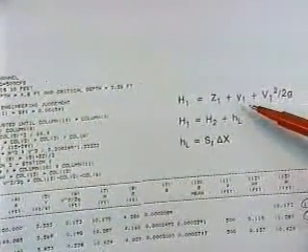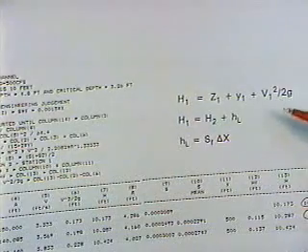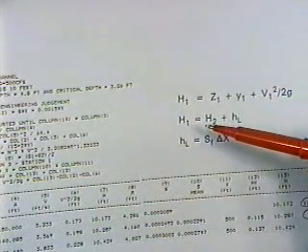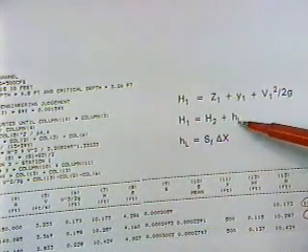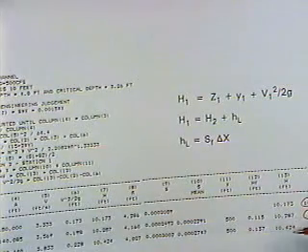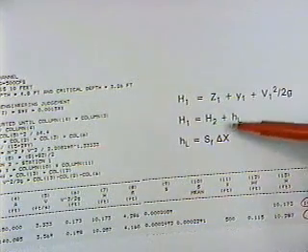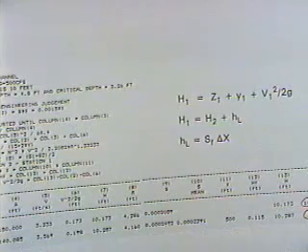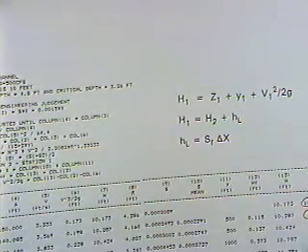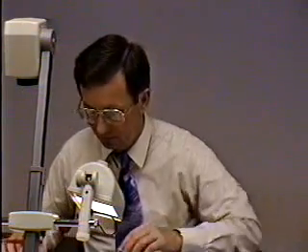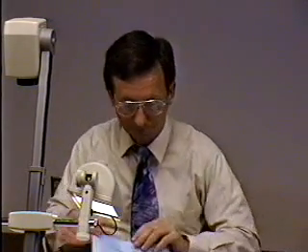The head's got to be equal to the elevation head plus depth plus velocity head, and then the head upstream's got to equal the head downstream plus the head loss. And so I've just set up the algorithm using both of those terms, and you just have to iteratively do it. And I think I'm going to move on unless you've got comments or questions, and take a look at conservation of momentum.